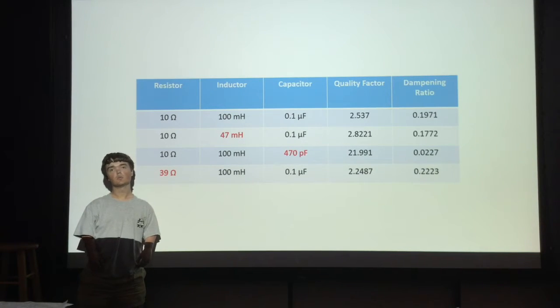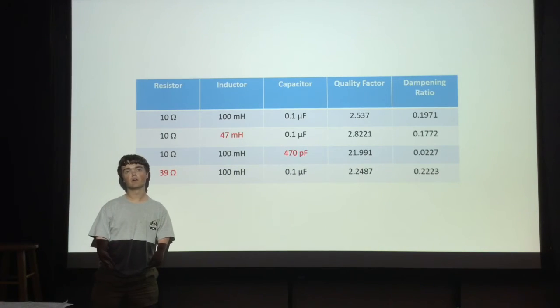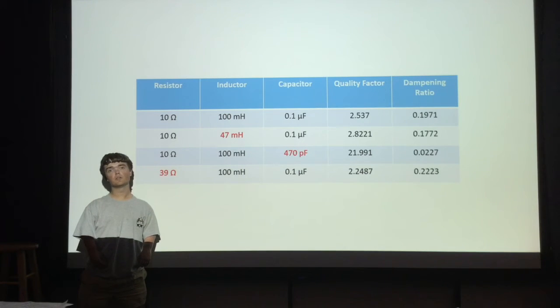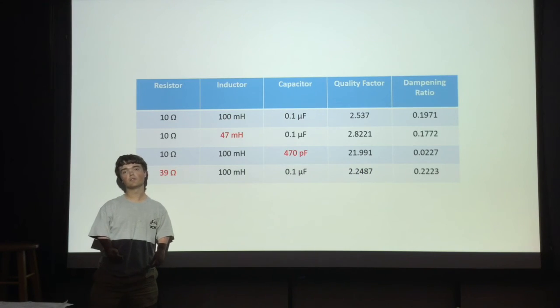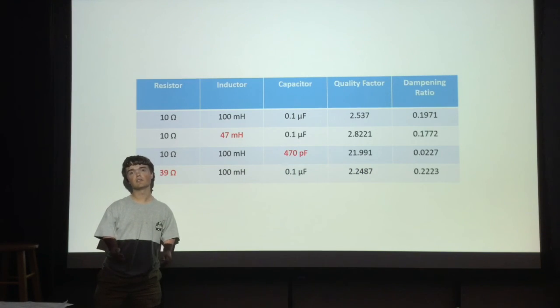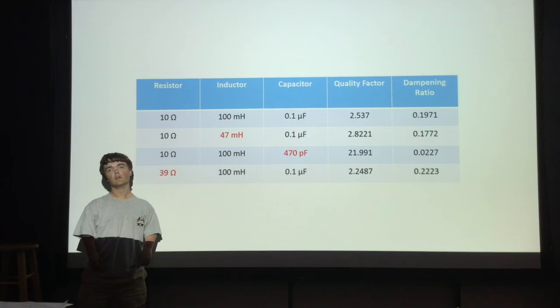Another problem we encountered was burning the power resistor, but we did fix that by using the 4 power resistors instead of just 1. One last problem we encountered was having to estimate with the cursors on the oscilloscope. Particularly, we're trying to find the minimum voltage of the capacitor, because we were using offset, and we had to kind of estimate where the middle of the transient response was, and therefore by having an estimate, it did throw off our calculations a little bit.